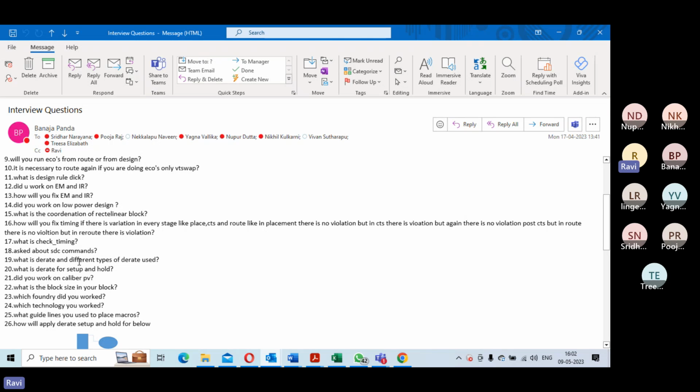POCV became an even more improved version, where it looks statistically at the behavior of the cell for a given transition, parameterizes it, looks at what its variation would be, and does the computation accordingly.